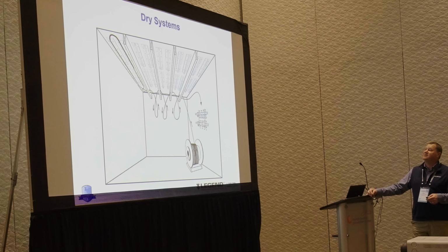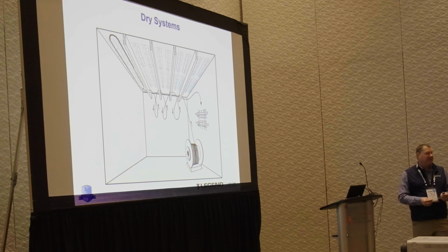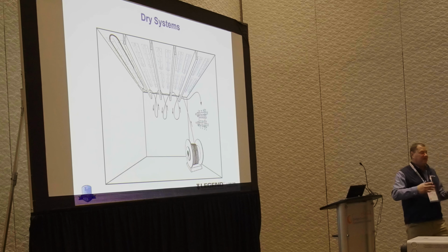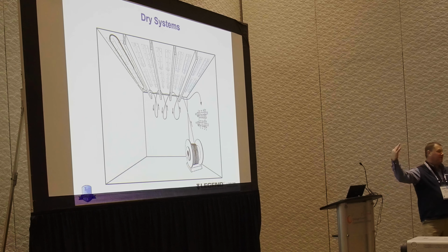Make sure the ends of these things are not pinched and tied tight. You know, when tubing expands and contracts, this is a good example. In this situation, you could be going from 70 degrees to 140-degree water. It shuts off, gets down to about 70 degrees in there, it kicks on, 140-degree water is in there. You got a 300-foot loop that's growing 21 inches.